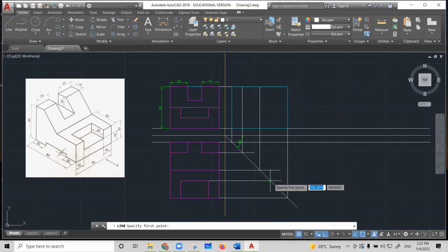So take the projections. At this point, here you have that point of contact. Then you will be taking the projections for surface contact, or you can start drawing the lines one by one. So this complete line is visible to you. I will be drawing this line from here at a distance of 20 millimeter. Then from 20 millimeter, I will be going 5 millimeter up.